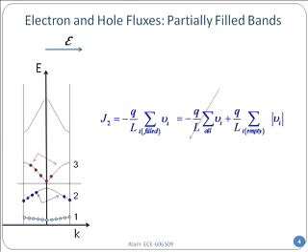Because then you see there are millions of them, so I don't sum them all. There are few empty states. I focus on them. I assign a plus q charge. Look at that, I have, instead of a minus q over L, a plus q over L left. So I assign a plus charge and let the holes, in this case the empty spaces, move in the same direction as the electron, with plus velocity.